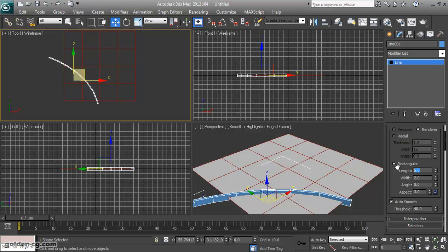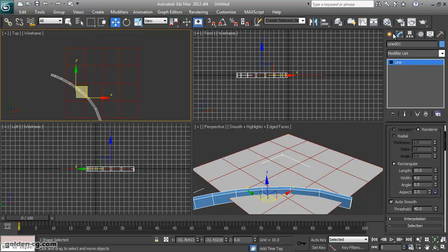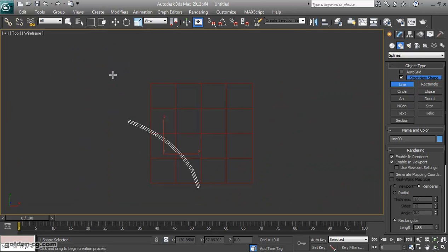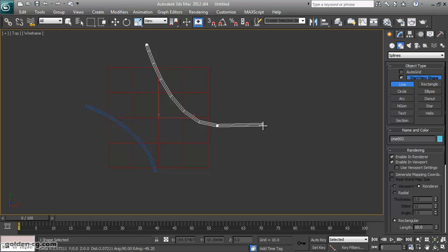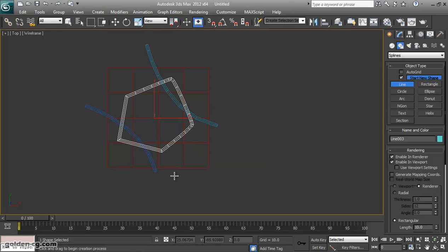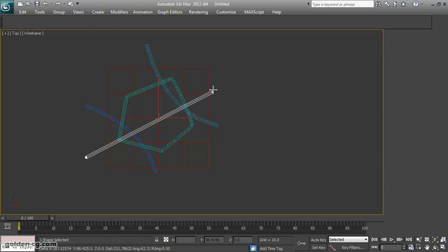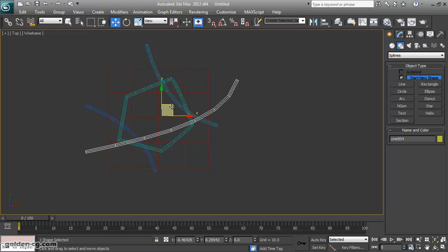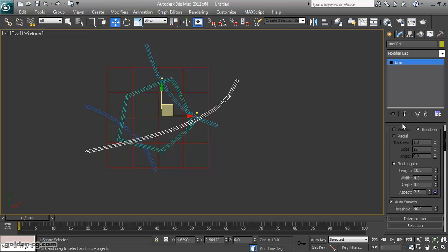The length I choose the tenth, but it is not really important. I just want you to see it taller and you can feel it. The width of my road I choose the 4. Okay, once I finish the setting I will start creating the other roads, just something random, and after finishing it I can choose them and set them, change the size and other things. So now I just try to refine them, the position, place and the shape.